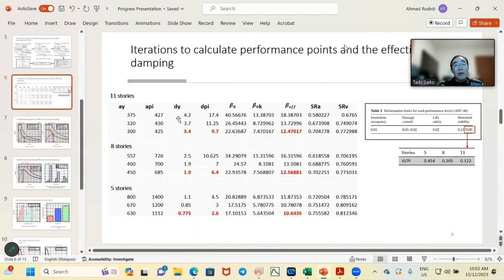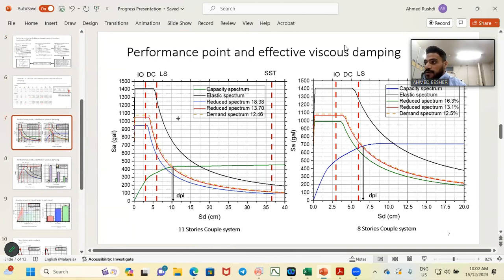So how do you get the ultimate? I get the ultimate point from the highest point on the pushover curve. For example, you can extend any. If you push more, the ultimate point will be more. I tried this, but it was in the same range. I tried to push more, and it increased, but not with a big percentage.